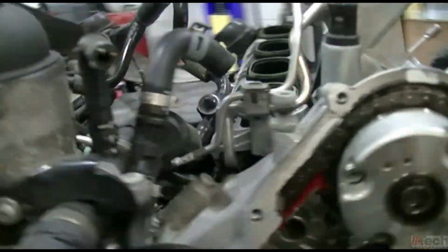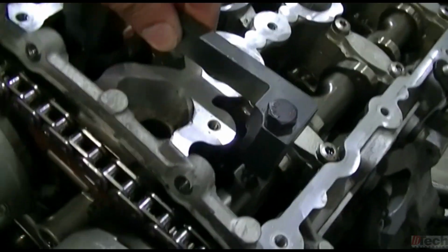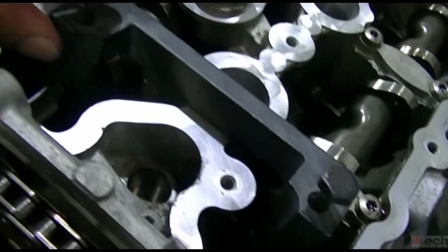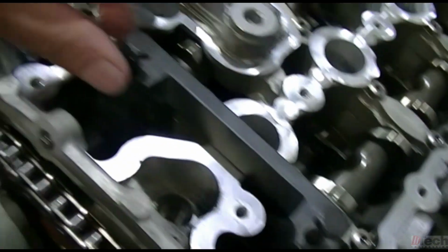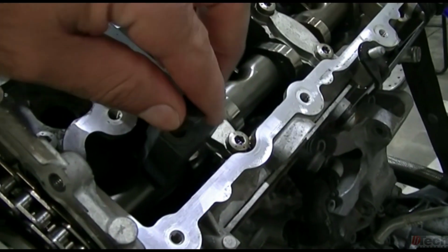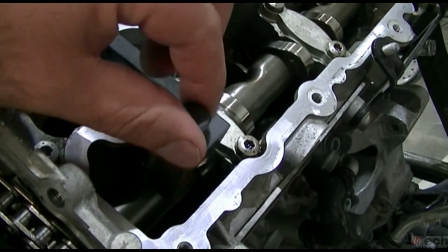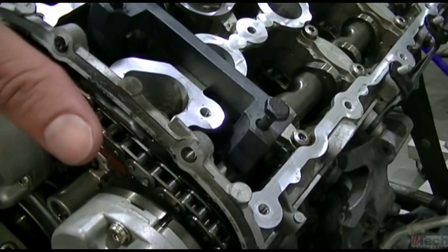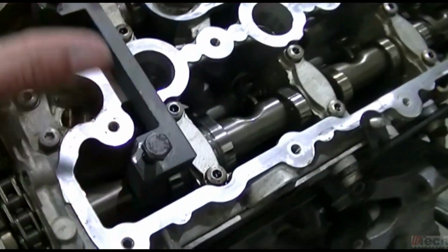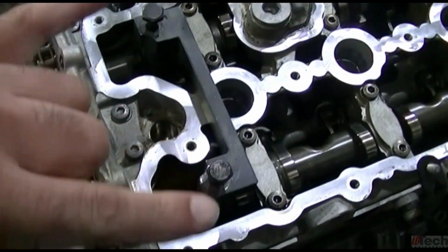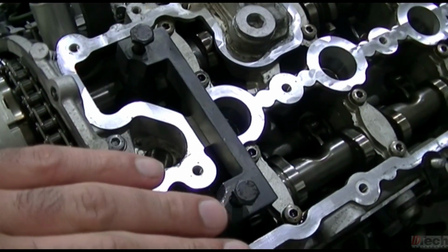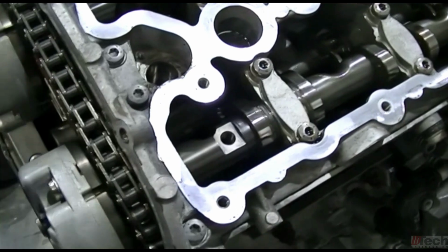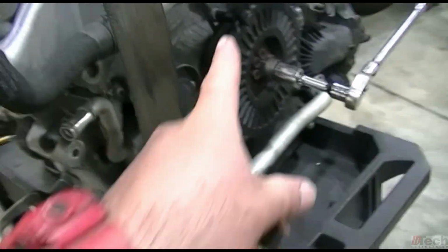And when I was setting this side up, I noticed that, see, this one's already stopping. This one's not even lined up. So this is bank 1, the one with the trouble codes. The cams aren't perfectly lined up as far as in the true correct position of being flat up and down when being in the locked position.